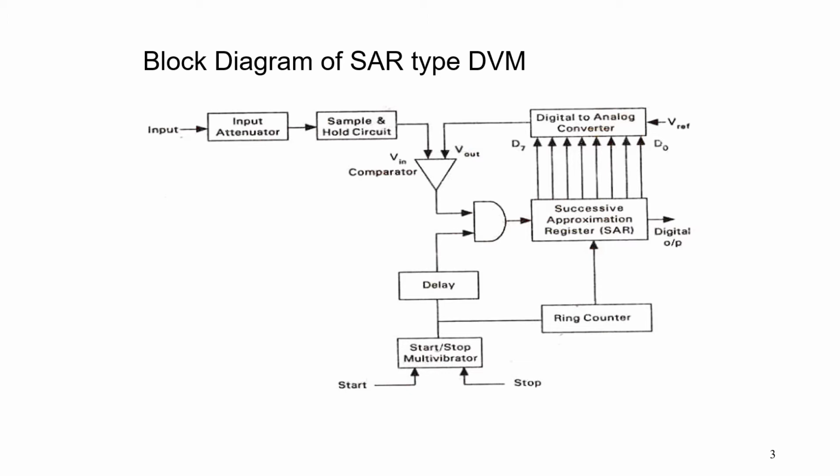The digital instrument basic circuits involve the use of logic gates and flip-flops. A logic gate is a circuit that produces a desired high or low output voltage when its several input terminals are all at the prescribed high or low input voltage level.